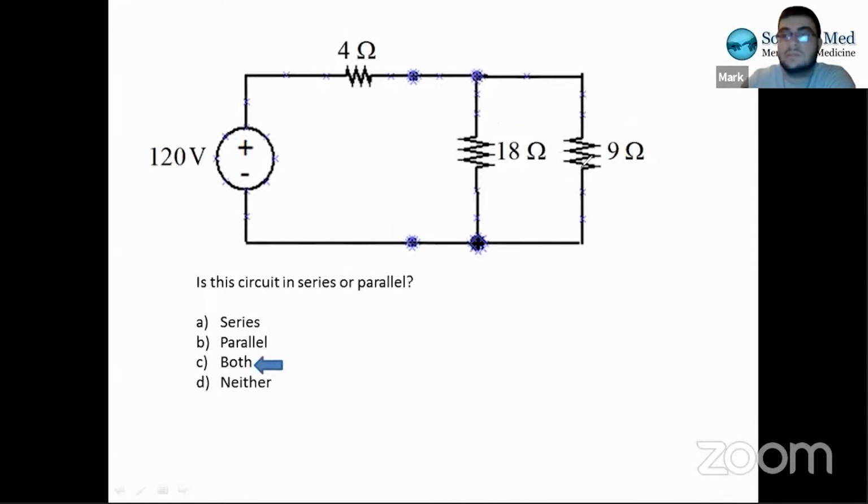How would we work with this, right? Well, we use the same exact rules that we use for anything else. First, you would find the total resistance of these two together, as if they were just two resistors in parallel, and then you would combine that to get a total resistance of this combination, and then you would add that to this in series.